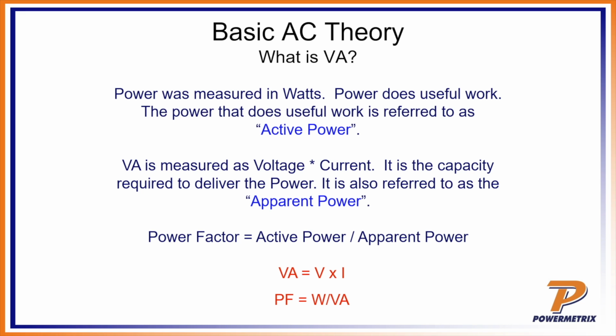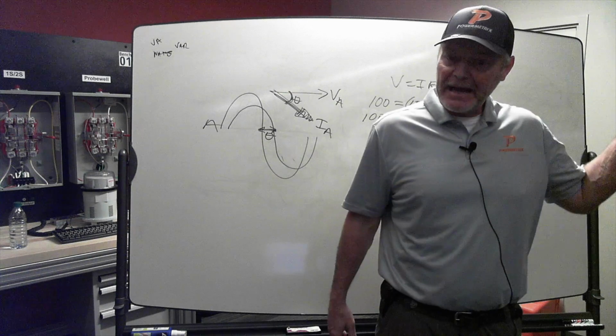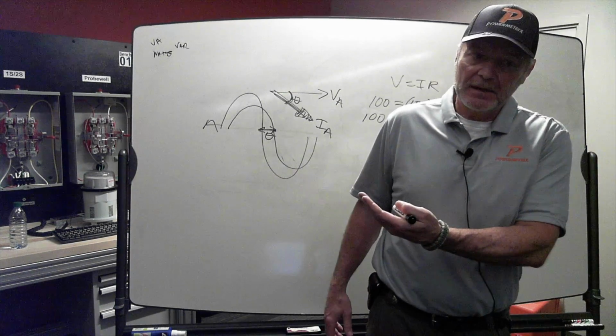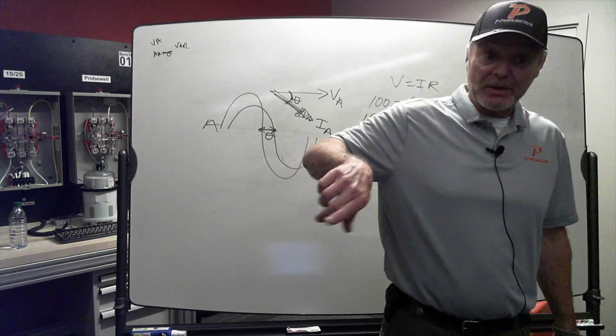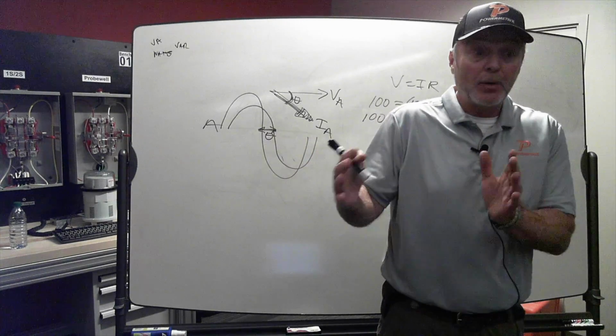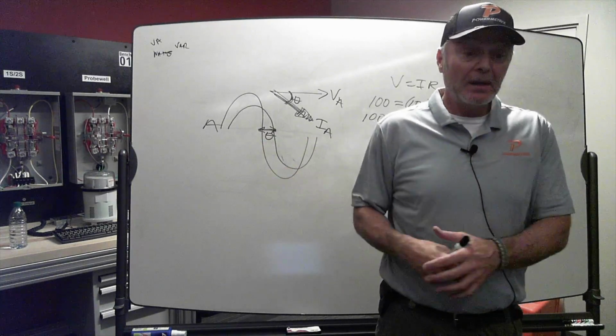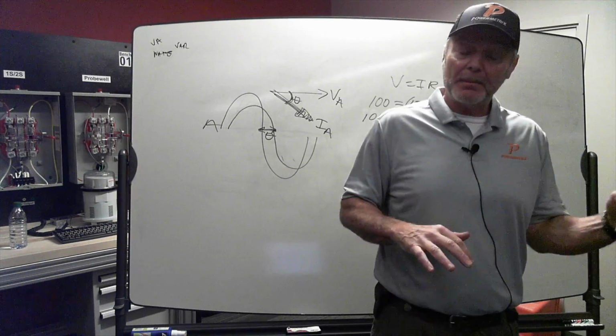The way that I look at apparent power, if you think about it, is that the transformer sitting out on that pole is so many kVA, right? It's the old water tank sitting there full, just waiting to do work until you open a spigot. Then the water starts flowing, and that's when the customer starts turning everything on and the transformer is supplying that power. Watts is what is used by the customer inside. Of course, we use our calculations to get to kilowatt hours eventually to bill them. That's the difference between active power and apparent power.